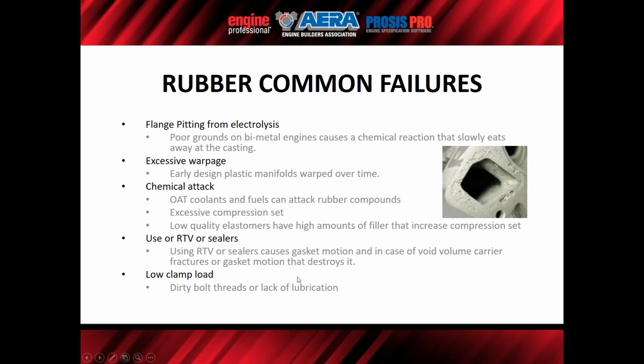One more thing on this that I'm just now thinking of is a lot of these earlier engines back in this generation, before E85 was out, you got people that try and utilize E85 gas in these engines, and those seals were not designed for that ethanol blend.